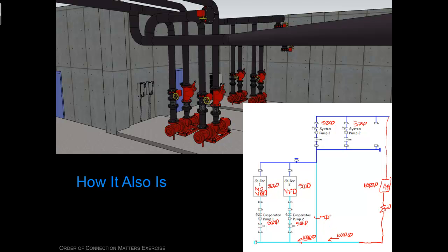And it's purely by virtue of how we designed the system. And you have to believe again in conservation of mass and energy. But if 1,000 gallons per minute come in here and we don't create or destroy water, and 1,000 going out there because of how these pumps were selected and designed, there's no flow in this bypass. Okay, the water comes out of the chillers, 1,000 comes this way, and then 1,000 goes out to the load and completes the circuit. Okay, so that's a theoretical operating point.